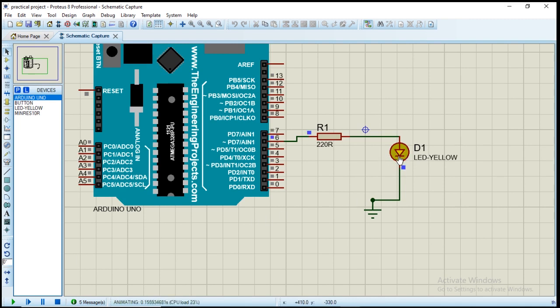You will see some changes based on the value we change in that analogWrite. Once you change that value, you are changing the voltage. So that is what we mean by analogWrite. The voltage is changing. It's not just 0 volts or 5 volts. You can get 2.5 volts, 3.5 volts, depending on how you change the value.